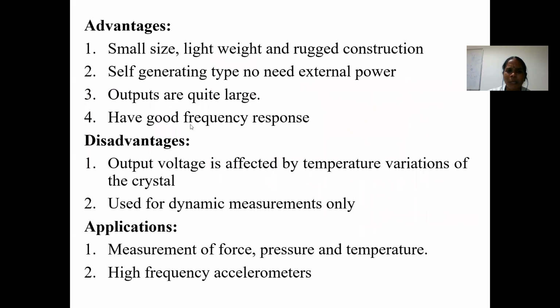Okay. So the advantages of piezoelectric crystals or transducers are its size is small, the weight of the crystal is less, and it is rugged in construction. It is a self-generating type because we are only giving a pressure, right? No external power is used, and the outputs are quite large and have a good frequency response.